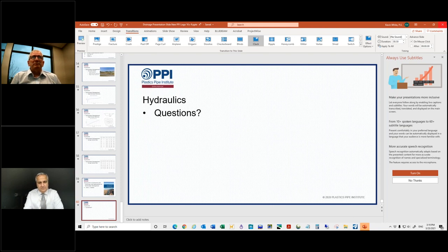For real extreme events, I don't know that we've had enough period of record to know that we're getting 100-year storms more frequently, but we are definitely getting those 10-year, 25-year, 50-year storms more frequently. And so are people designing for it yet? I don't think so. I don't think there's been a push yet to start designing for those larger frequency events.